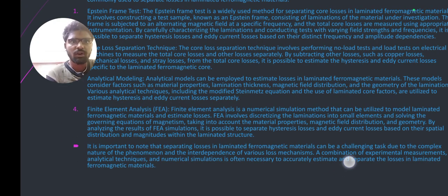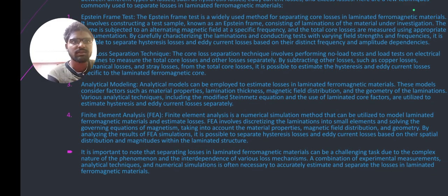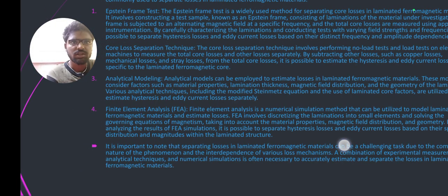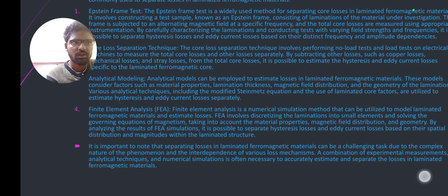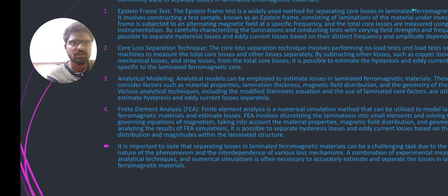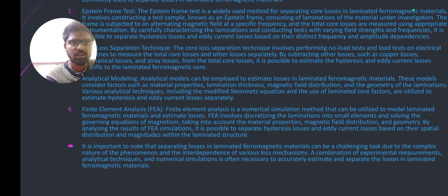It involves constructing a test sample known as the Epstein frame. Core loss separation technique. The core loss separation technique involves performing a no-load test and a load test on the electrical machine to measure total core losses and other losses separately.